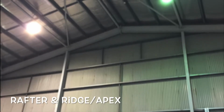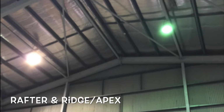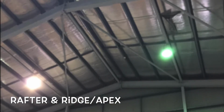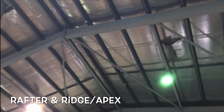A rafter is a type of internal beam that holds up the building's roof loads or weight from above and constitutes a roof framework. It is connected between the columns and beams at one end and the ridge or apex at the other. The ridge is also another horizontal member like a beam at the top of the structure. Purlins are used as a smaller horizontal beam member that sit on top and are supported by the rafters. Purlins are specifically used to carry the roof deck sheeting loads.